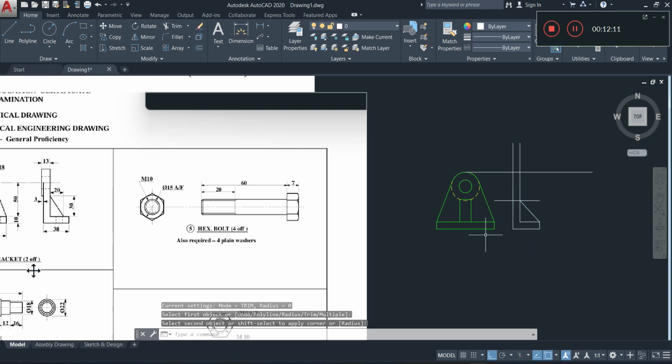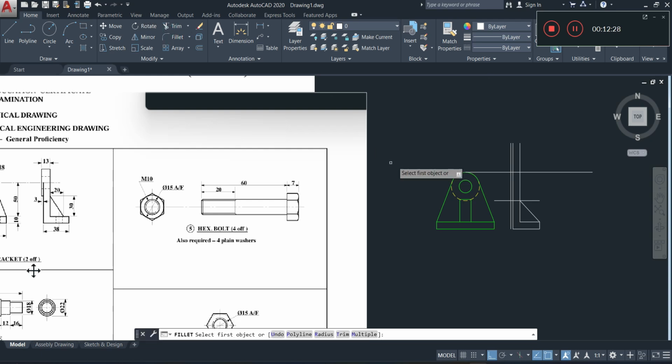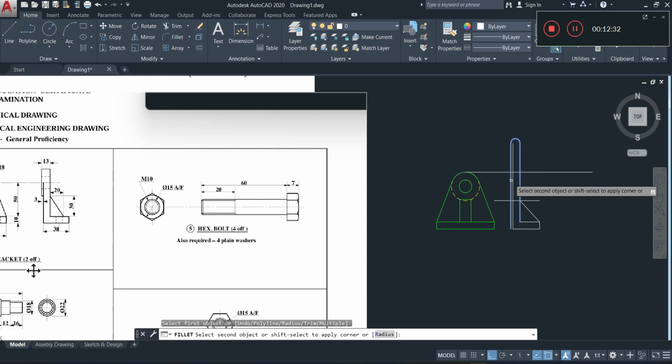Alright, now once that is done, we can offset that little 3 portion there to the front. So O, enter 3, which is right here like that, and then further cleaning up, again the option is yours, whether you want to trim, fillet, or chamfer.